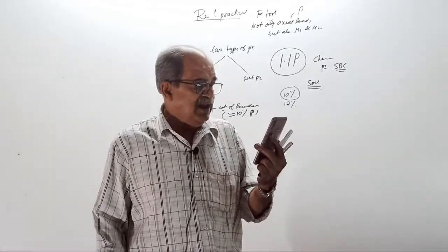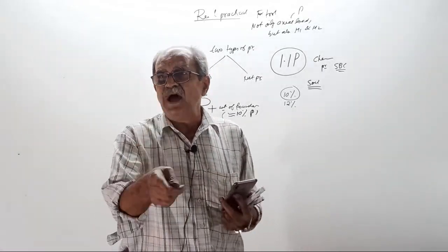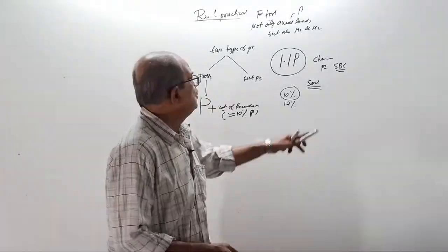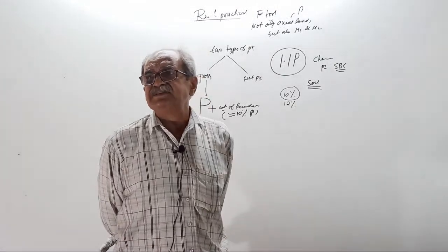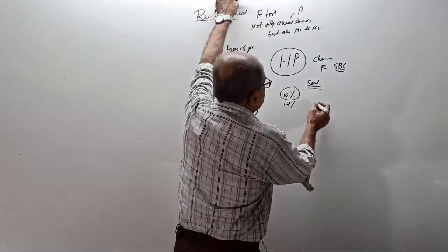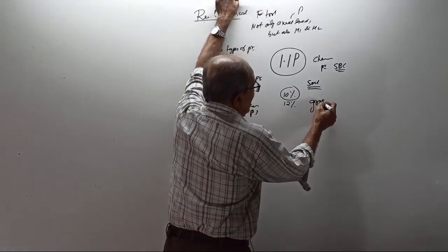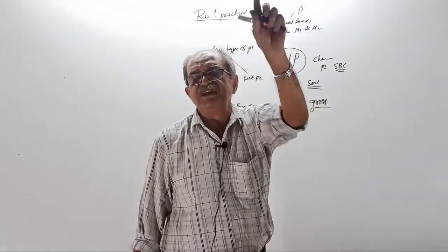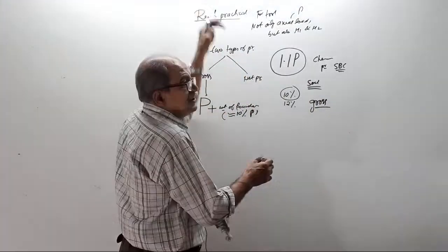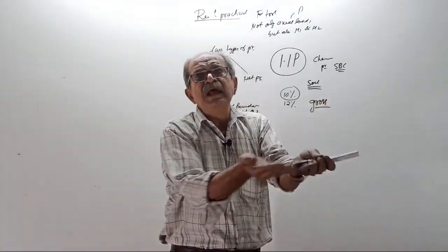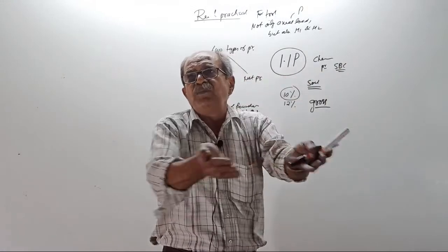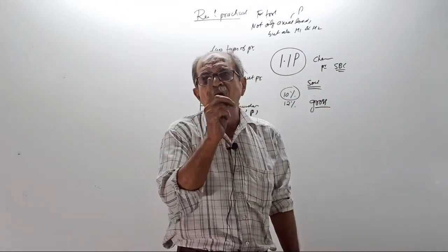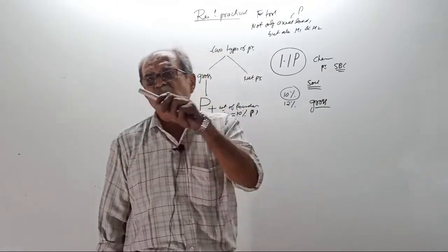For the soil, weight of foundation also counts. So therefore, when you want to ensure that soil is safe, you have to always consider gross pressure. And remember, ETABS also will find gross pressure. But when you find bending moment and shear force for the footing slab, at that time you should not consider gross pressure. Tell what you have to consider.